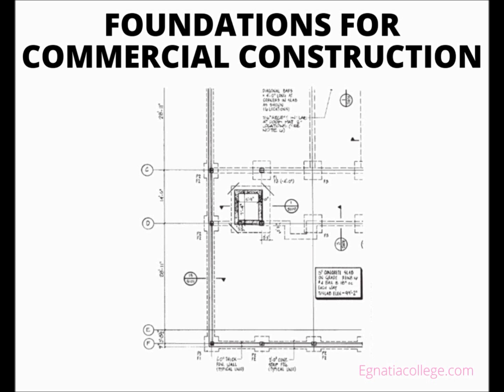To support these loads, the foundations of heavy buildings are carefully engineered by structural engineers and are more heavily reinforced than the foundations for smaller buildings. Generally, continuous wall foundations are similar to those for smaller buildings. They consist of a spread footing that supports a continuous concrete wall. Because of the greater size of the structure, the footing and wall may be more massive for a heavy building, and will probably require more and larger diameter reinforcing steel.